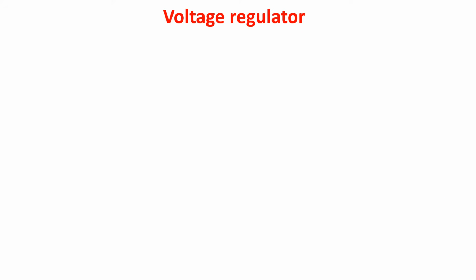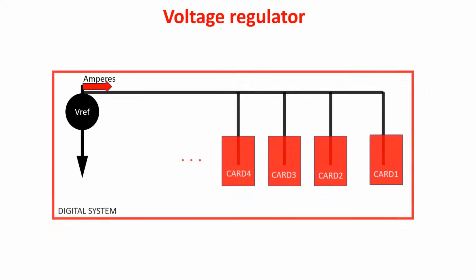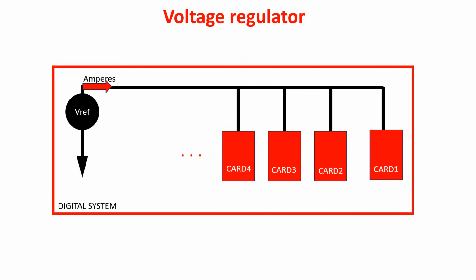Regulators can be seen as voltage references capable of supplying a lot of current. Back in the early 70s, digital systems were spreading out. According to Widlar, they had relatively high current requirements, but there were a number of problems associated with using one centrally located regulator. Heavy power buses must be used to distribute the regulated voltage. With low voltages and currents of many amperes, voltage drops in connectors and conductors can cause an appreciable percentage change in the voltage delivered to the load.